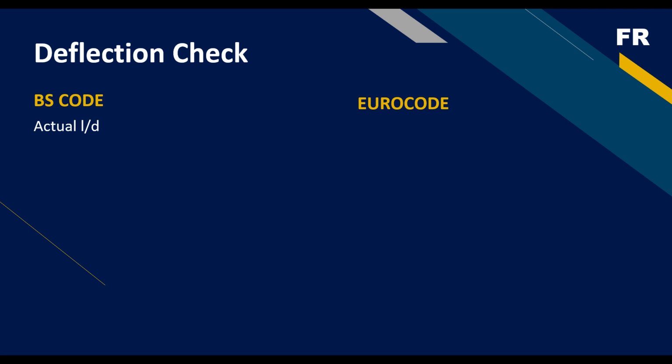So if you look at the Eurocode, the same thing was also recommended, even though the Eurocode tried to buttress or provide other methods like the calculation method. You can also find the calculation method in the BS code, but it is not really common compared to what we have in the Eurocode. So in a nutshell, in the two codes, the method of checking for deflection is the same: the basic span ratio. These are the two methods you find in the two codes.